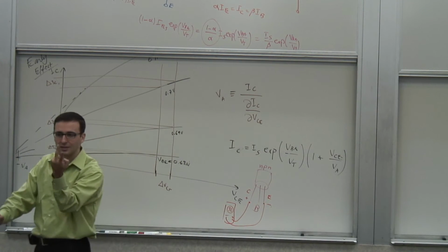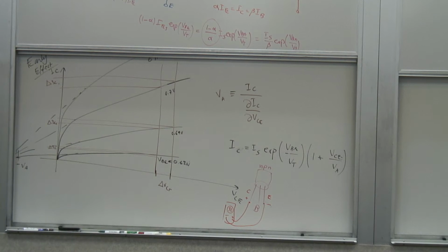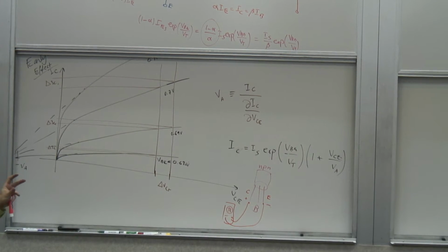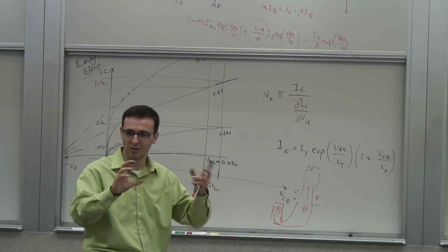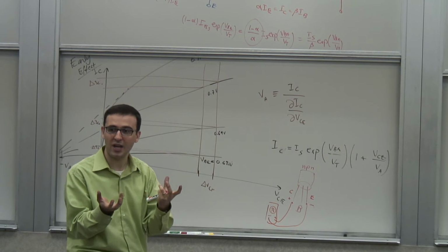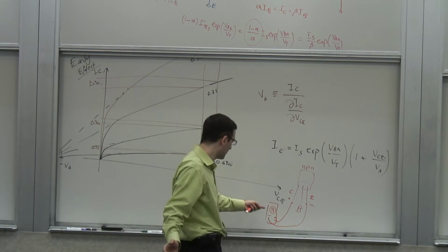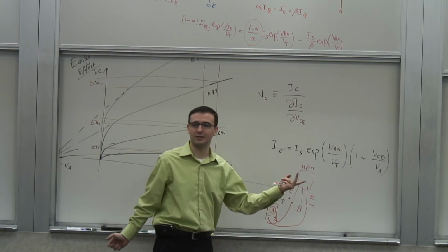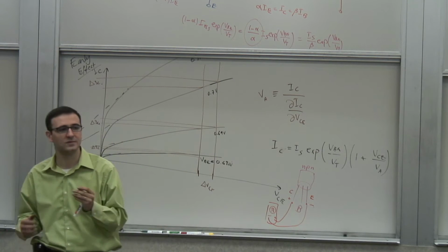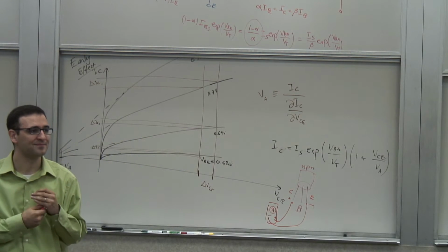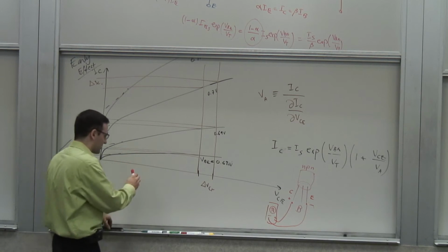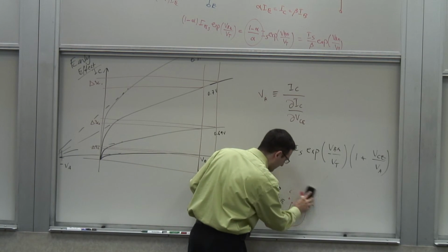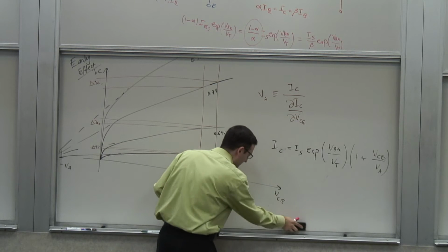But now, if the transistor is reversed, beta is really small. That charge is not enough. In case of some transistors, you may see a change in resistance in both directions, but the change would be substantially greater when it's connected this way than the other way around. Does that make sense? Okay. All right, so that's just a little piece of trivia, but it's based on what we learned about the transistor.